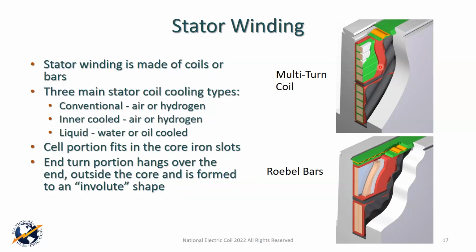Going back many years into the asphalt days, a lot of the machines had very low volts per mil ratings, some of them even down around 30, 40, 50. Over time, as insulation systems progressed and we tried to get more out of the machines, volts per mil started to rise. Going back into the 60s, it wasn't uncommon to see designs at 50 and 60 volts per mil.